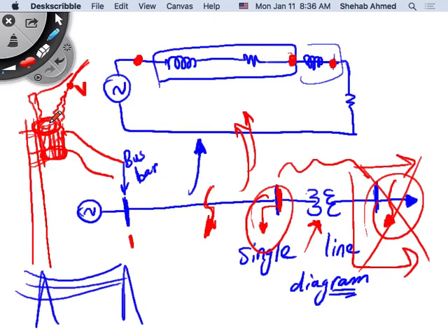And of course, practically, even though these voltages are not close to 30 kilovolts, you still don't want to bring them too close because we're not talking about air now. We're talking about rain, dust collecting on these insulators. These insulators have a body with a certain shape. This shape has a tortuous path that is designed so that it is difficult for anything to build up on it. And the materials are selected such that it is difficult for anything to stick to them.